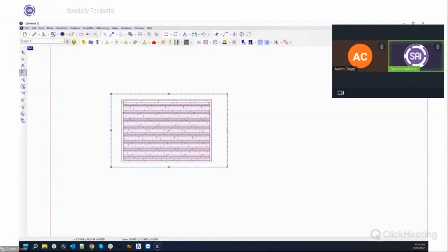If you're using a ball end mill, yes. If you're using a regular end mill, you probably still would run into a little bit of that, but that's where you'd want to increase the overlap just slightly. Normally it's at 50%, and I believe at 50% you probably would run into some of that. So you'd want to increase the overlap at least 10 to 20%, I would imagine.